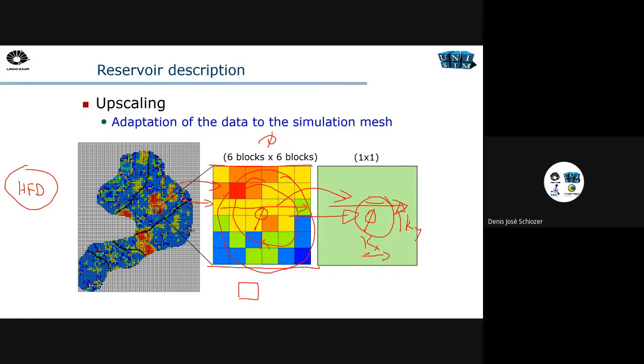Of course, this is a little bit more precise than using a block average. For example, if I was in that case that has a barrier here, of course, I would have a vertical permeability here, but not a horizontal permeability here, a Z permeability, not an X permeability. So this numerical model would be able to emulate all these aspects.